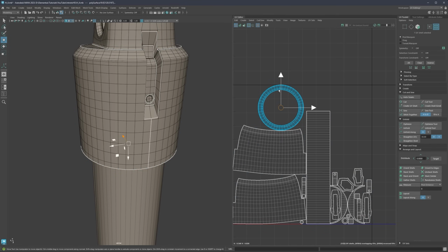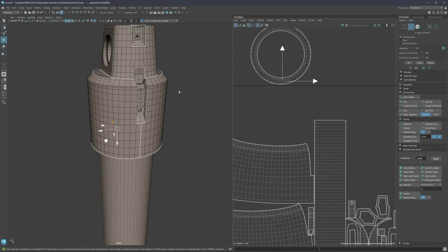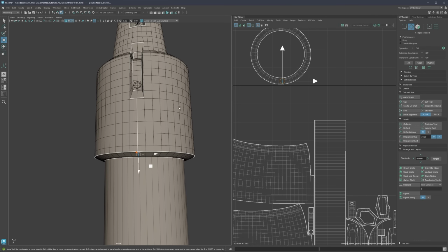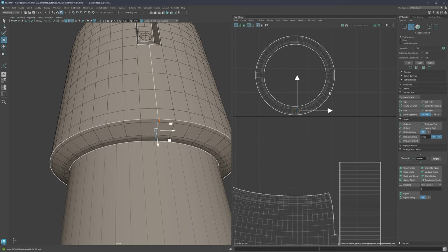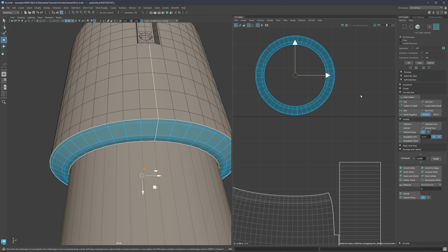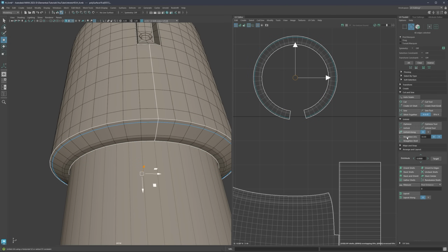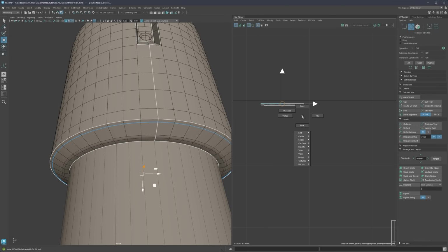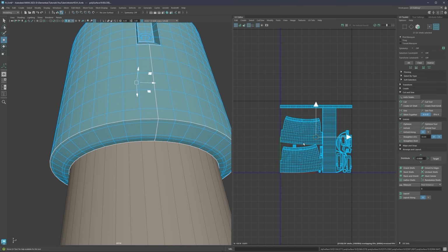And the same thing, for example, now with the circles. If you wish to, let's say, create more space, you can also find where the circle is, for example, it's right here and the seam actually matches, you can also create a cut there. So let's say create a cut, go to UV shell and then unfold that and maybe try to straighten it with straighten shell, and then go to UV shell again and straighten UVs. And now it's pretty small, but when we select everything and go to layout, it should even itself out.